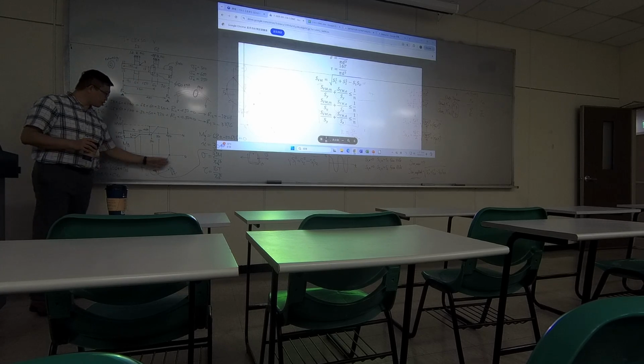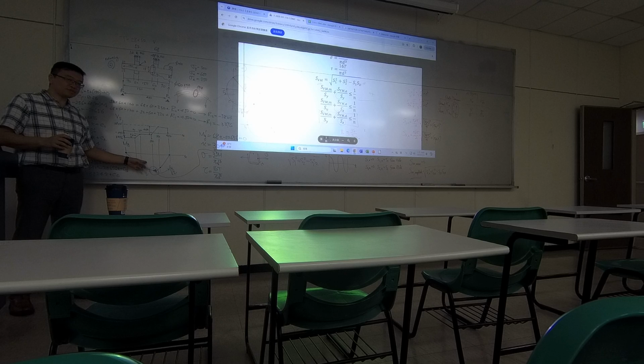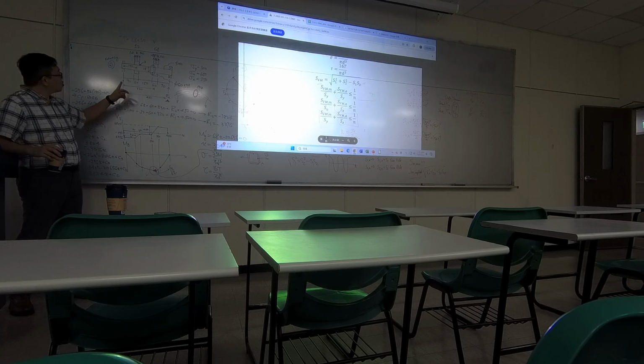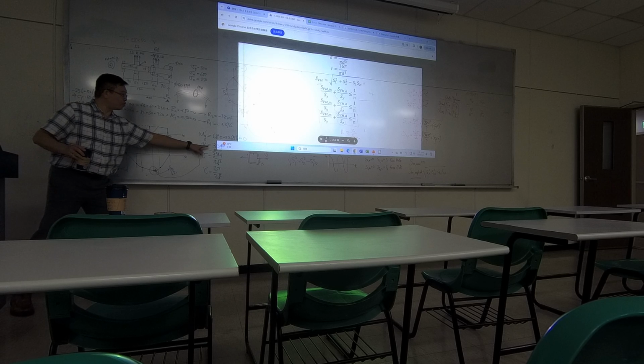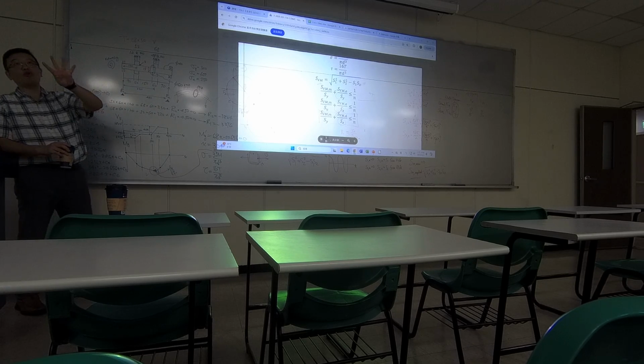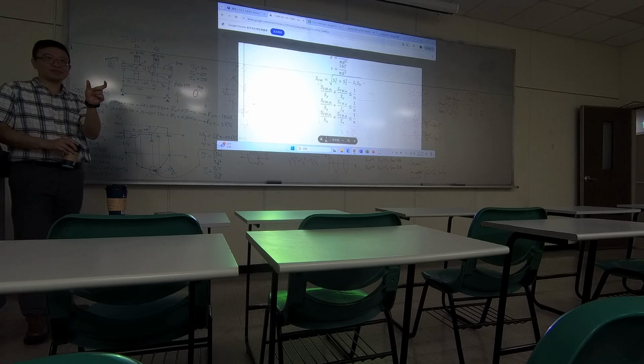When we solve for the moment diagram, we know the worst bending position is located at 304. It's not right at the position with the highest stress concentration. The position with the highest stress concentration should be located at 300. So there is a 4 millimeter difference.